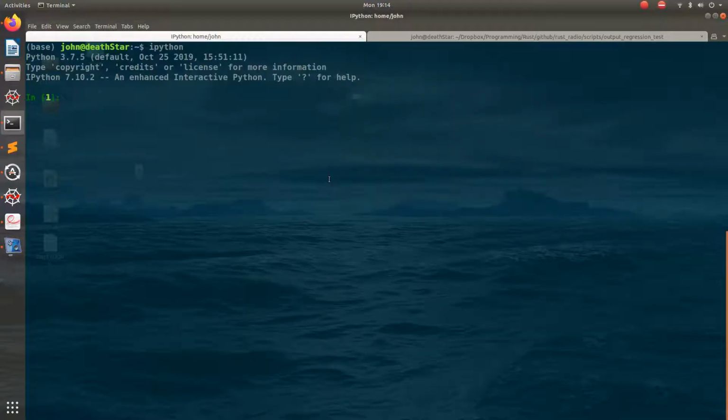So this will be how we figure out the frequency difference over that interval. So we start with the change in time between the two captures. So that was 4.16 microseconds. And I'm going to put the units off to the side so we can check it as we go.